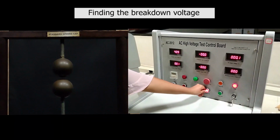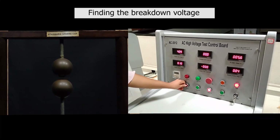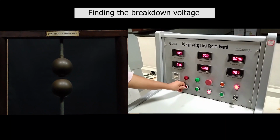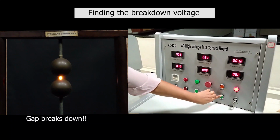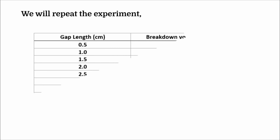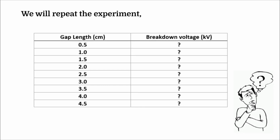We increase the voltage as in the previous instances, and note down the voltage at which breakdown occurs. Again, we conduct the same experiment from 0.5 centimeters to 4.5 centimeters in steps of 0.5 centimeters.